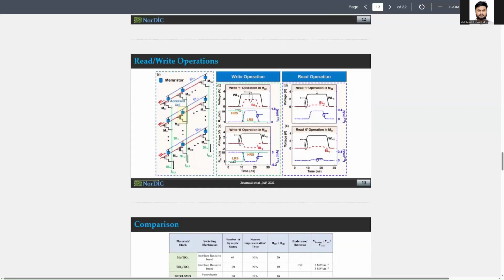What we need to change is the bit line voltage. We are providing the word line voltage and bit line voltage, right? Here, the left hand side is the write operation, and the right hand side is the read operation. What difference can you see between word lines and bit lines? As you can see, the word lines have exactly the same wave shapes, so we do not need to change them for the write operation. We have already done the read operation. As the word line voltage is exactly the same for the read and write operation, we are not going to change the word line wave shape, but there is a difference between the bit line voltages. For the read operation, we have used a read voltage, and for the write operation in the bit line, we will have to use the write voltage.